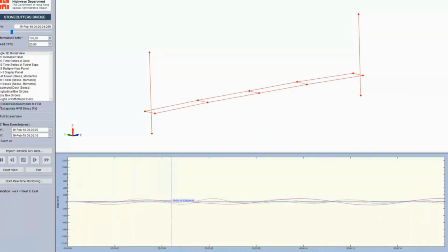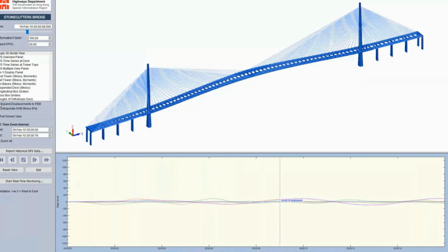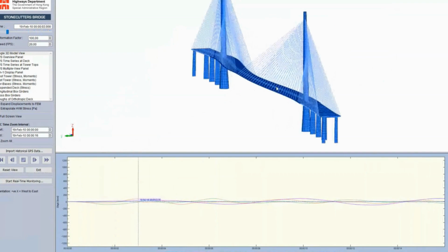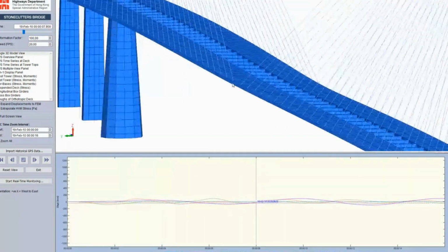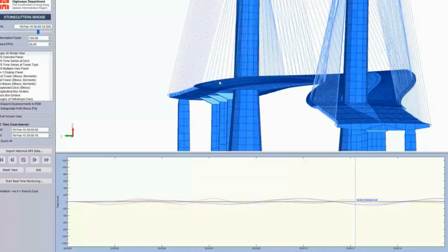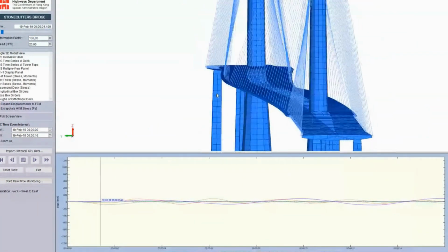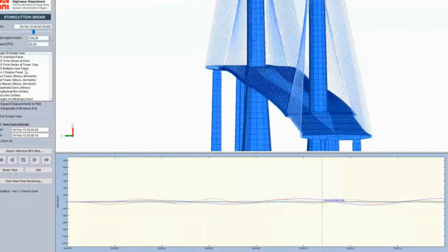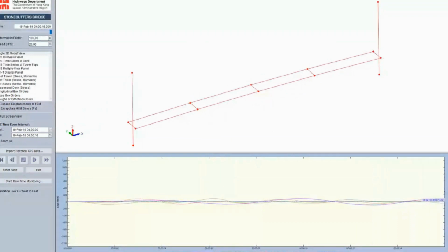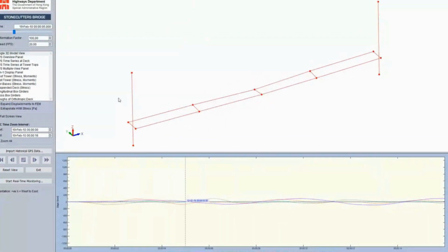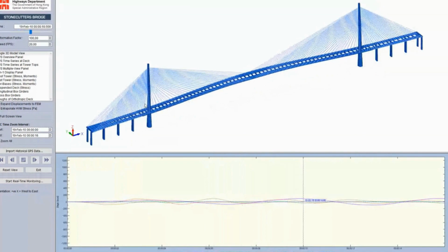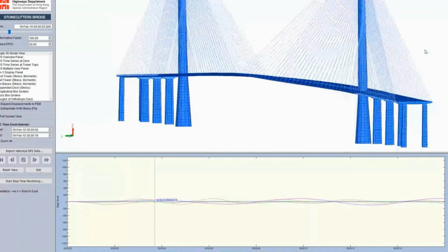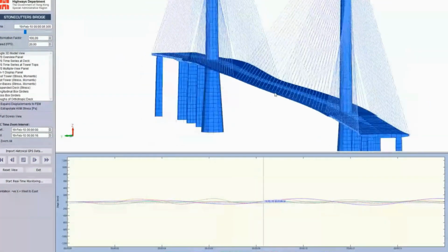Now we can do the expansion to FE by clicking here. And now we see the FE model, how it moves. You can see the bridge deck. It's a bit exaggerated, of course, for better visualization, but this is obtained from this model. So using only 8 GPS receivers, we can simulate the bridge deck deformation and the tower deformation.